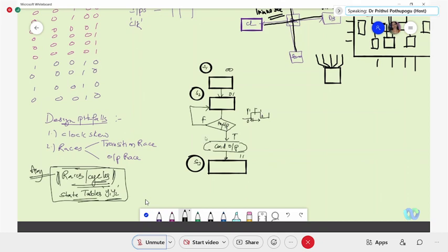And if the change in this input is happening very close to the clock changing from 1 to 0, this input, which is asynchronous, normally will be indicated with an asterisk on its top. Okay. If it is happening at a shorter interval, just near the position where the clock is going from 1 to 0, there is no sufficient time for the system to generate this conditional output. Straight away it is going to another stable state S3. Can we call this a race?